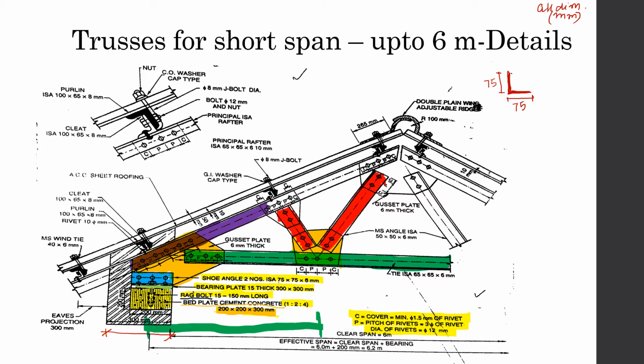So I've colored them with red. And as you can see, the principal rafter is going all the way up to the top at an angle, the angle which is called pitch. And the intermediate members are perpendicular to the principal rafter. So if this was at 30 degrees, you can guess what this angle is going to be if it is perpendicular there, and same for this angle.